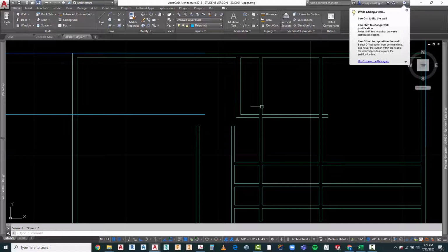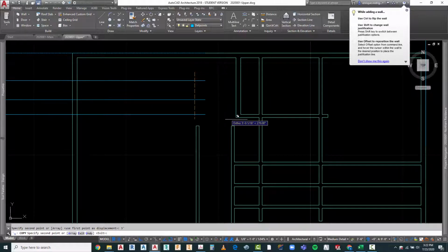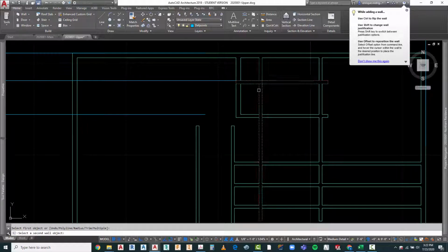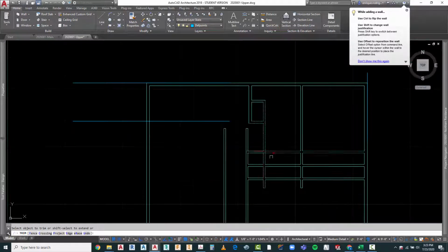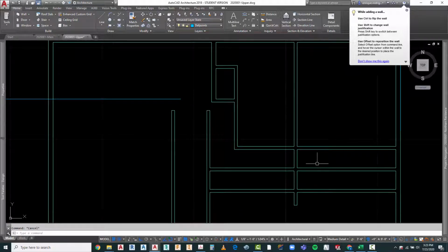And this is 3 feet here, so I'm going to copy this down as 3 feet right to this location. So what I need to make sure is that I'm using the proper math. So I'm going to go ahead and grab this and pull this over, and I'm going to copy this wall from this location to here. And what that's going to do is give me an alcove here for my toilet to work with. I can trim this out right here so that it's nice and clean. I can bring this across, fill this out of the way. Okay.